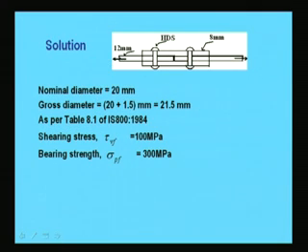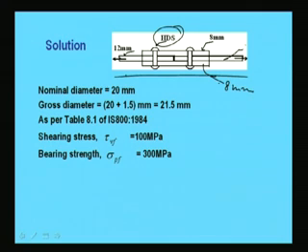So, the problem is like this, that two covers have been introduced of 8 mm, and hand driven shop rivet has been used. The thickness of the main plate is 12 mm, and so a double cover butt joint has been made.